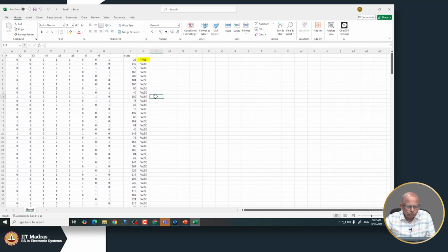So, this is what a linear feedback shift register is, and how does it help us? It helps us by generating random numbers. Many times we require random test vectors, and the LFSR helps us in generating them. The only thing is these are not truly random.